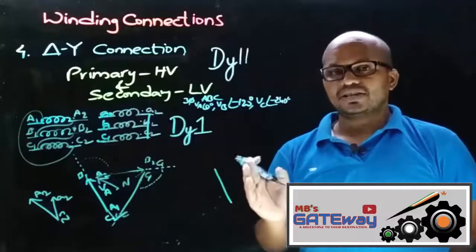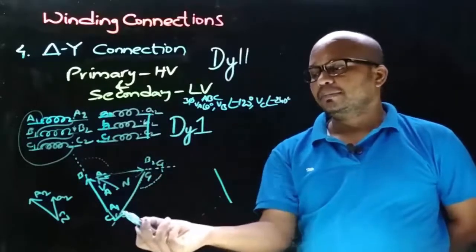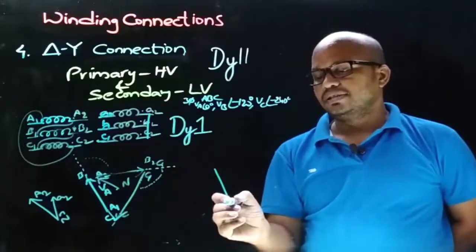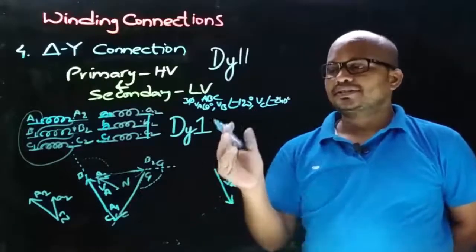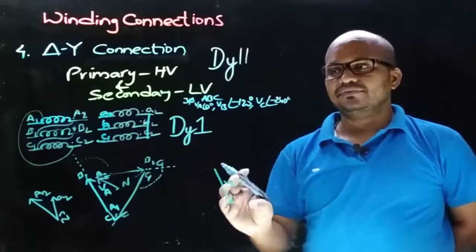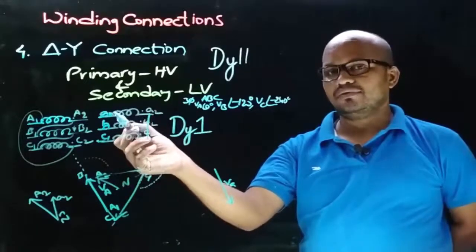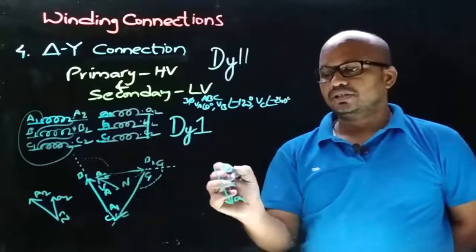This means the secondary side phasor direction will be opposite to the primary side VA phasor. As the primary side VA phasor is upwards, the secondary side VA phasor direction will be like this. Now let's decide the terminals: here we are taking the connection from the non-dot end terminal, that is A1. Therefore the arrow will point towards A1, so the other end will be A2.